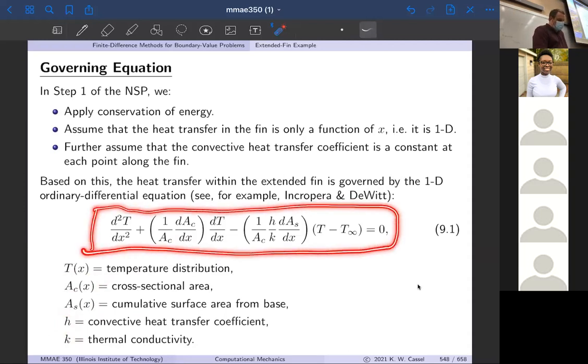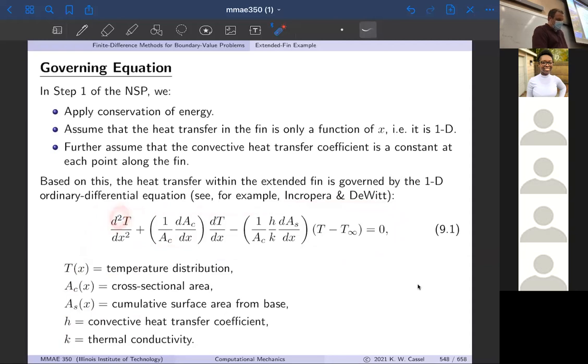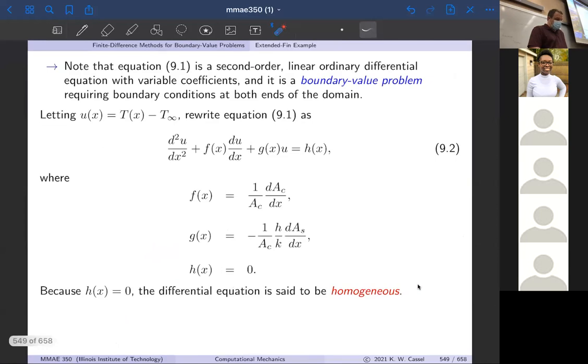It's second order, because the highest derivative is 2. It's linear, even though it kind of looks like a complicated equation. It's linear in the dependent variable T, because we just have a d²T/dx², dT/dx, and then a T term. All of this stuff makes it a variable coefficient ODE, but it's still second order and linear. So it's a second order linear variable coefficient equation for the temperature as a function of x, given all of these various properties of the system. Great.